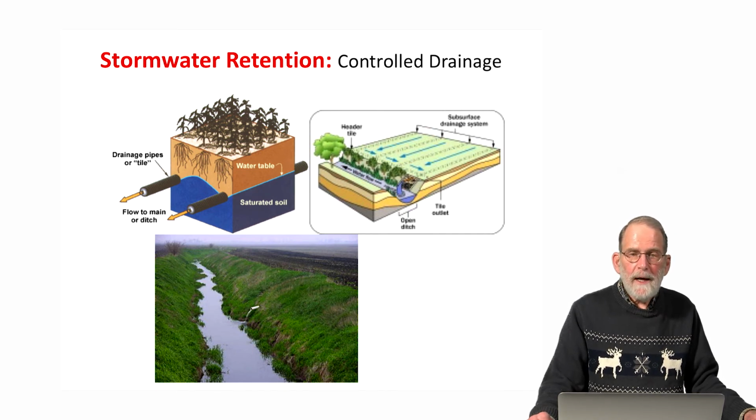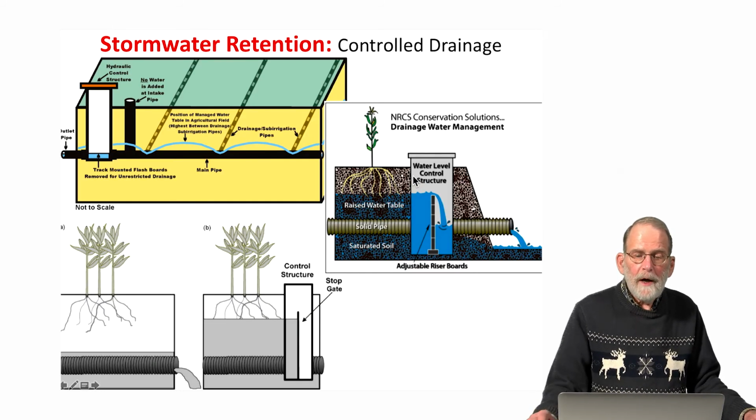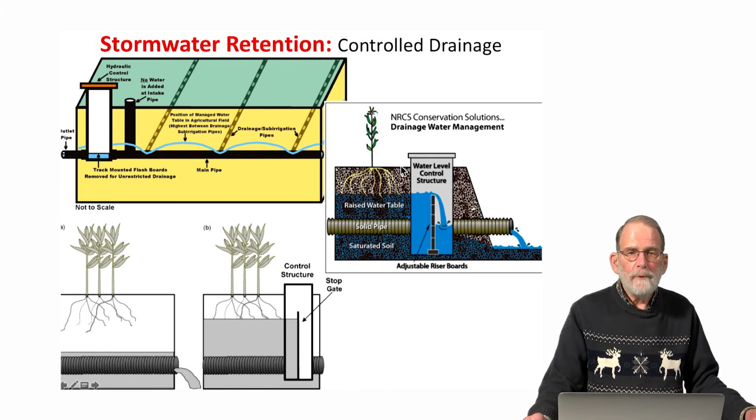device. And the design of this drainage device can be used quite strategically to moderate the amount of surface and subsurface flow coming out of the agricultural landscape. By using a series of valves and stop blocks, we can actually regulate how much of the soil moisture is going to be discharged at any one point in time. And by manipulation of the surface drains and surface grading, we can regulate the amount of surface runoff that's flowing.